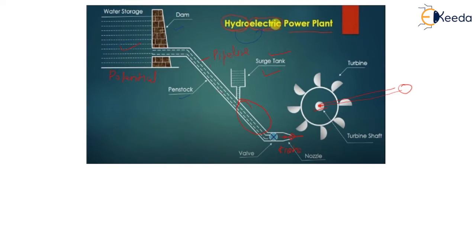When we close this, the pressure in this water will be very high, and this water will flow through here, and this tank will fill up, and the pressure here will be minimized. So the water hammer effect is avoided through the surge tank. This question can be asked in the GATE examination. So an important point: through this surge tank, we can avoid the water hammer effect.